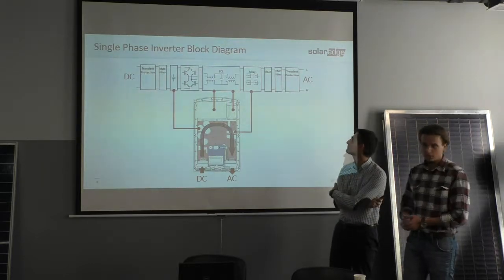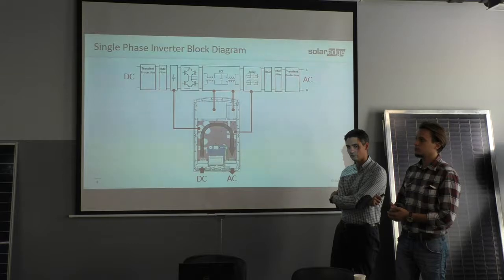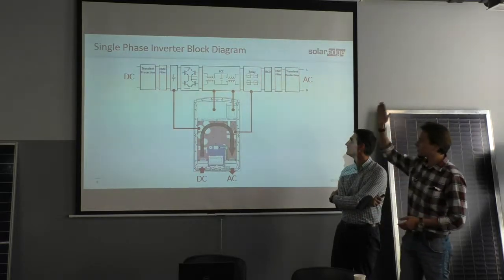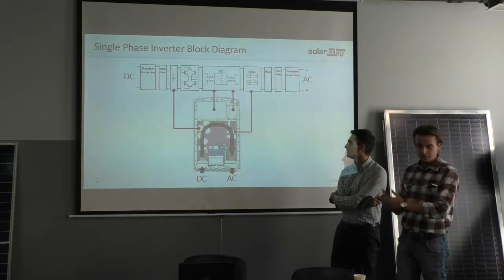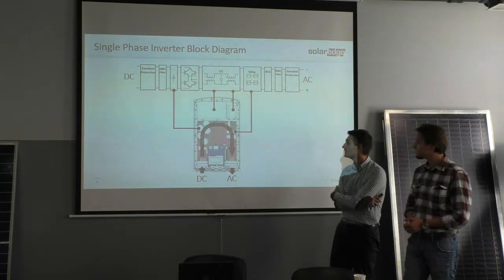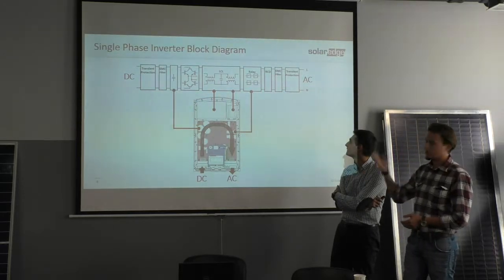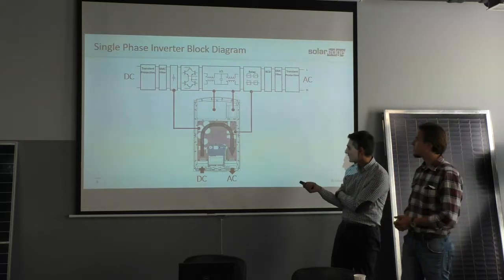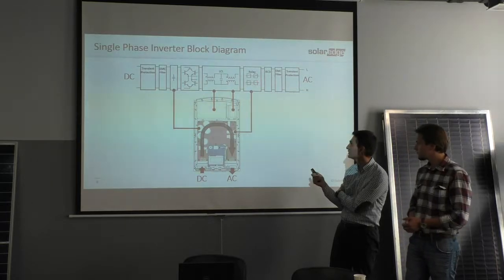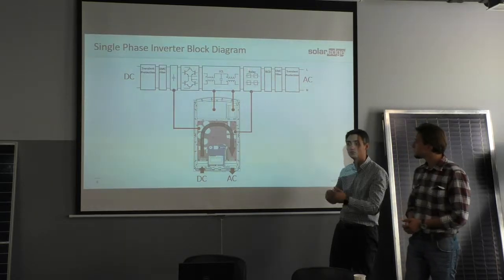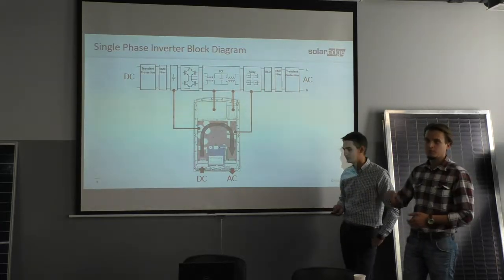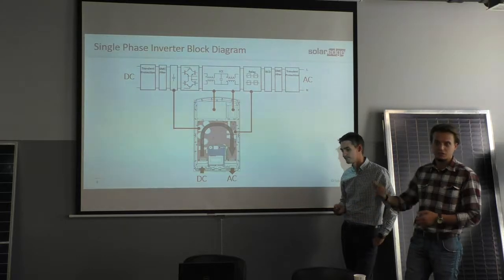That is basically how the inverter is built, as you can see. We have the input, the display is in the middle, and we have a relay that controls the conversion. Here and here we also have electromagnetic components, fields. We also have electromagnetic filters. Somewhere here there is an RCD, a residual current device connected to the relays to disconnect in case of residual current. We also have a switch that disconnects the system if there are voltage surges.